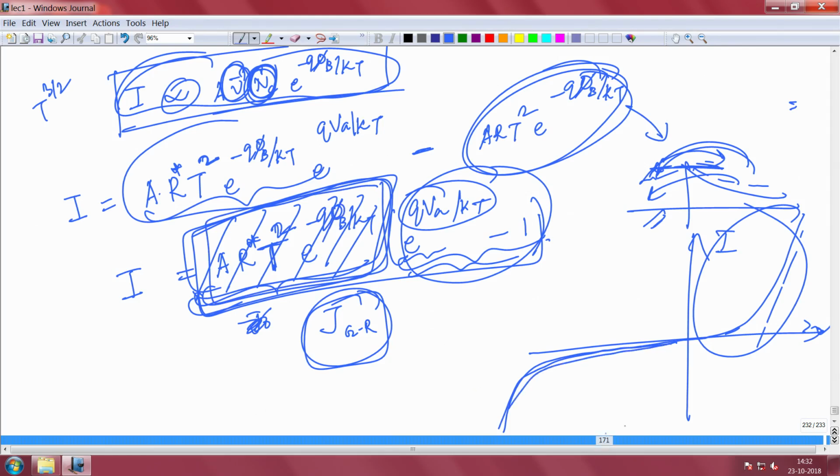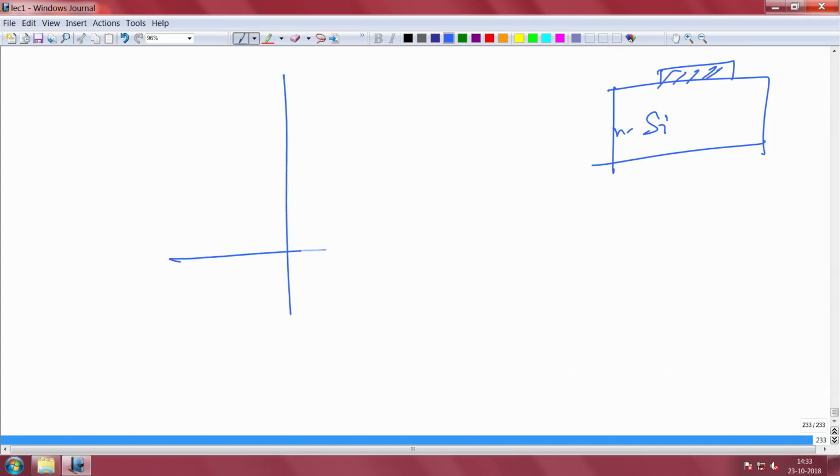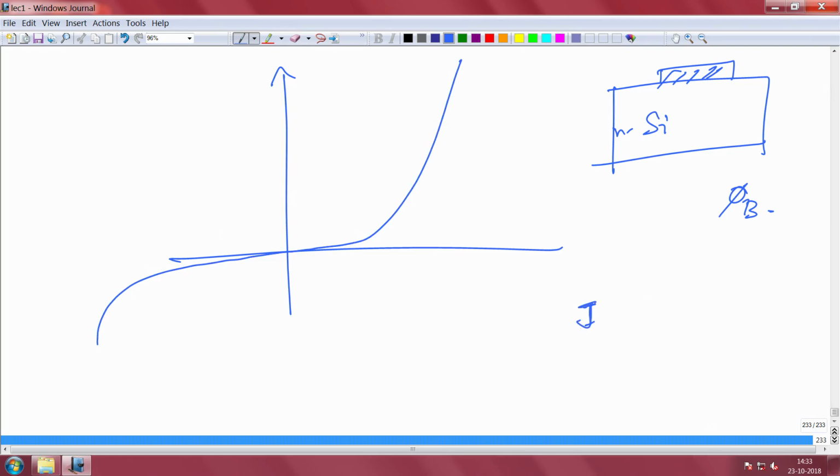So, how do you find it out? One of the things you find out from this temperature-dependent IV characteristic: you are given a metal-semiconductor junction, for example, this is N type and this is metal, and you are asked to find the Schottky barrier height phi_b. So, what you do is the IV, say at room temperature. You recall the IV equation, I equal to, or the current density J, with area taken into account, is some Richardson constant, that is constant, T square, exponential of minus q phi_b by kT, times e to the power q V_A by kT minus 1.